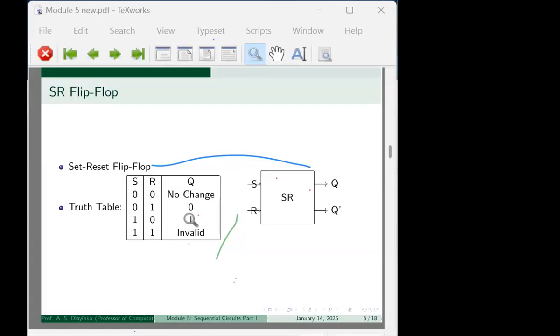Then when you now apply NAND, we said it's a special NAND. Applying NAND to this output, both of them will give us 1 instead of having 0 for the two places. Does it make sense? Both of them will have 1, 1. But you know, we are looking at a special case of NAND. When you have 1, 1, you have an invalid situation. So you need to be familiar with how this is done.